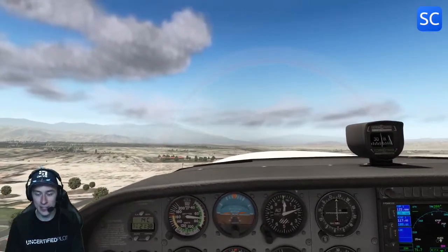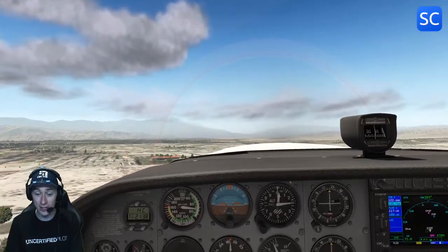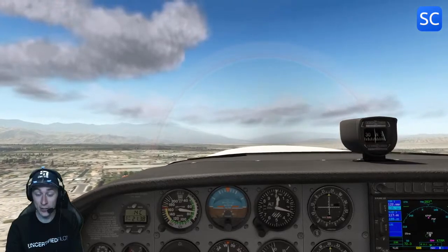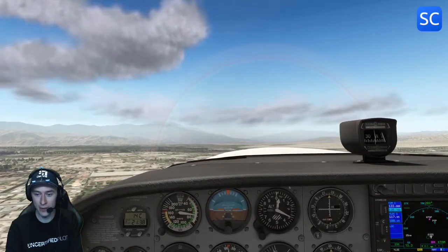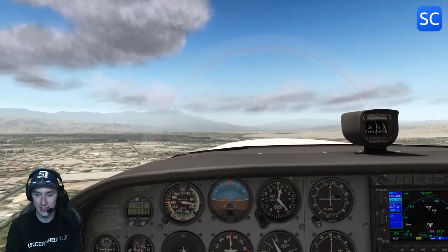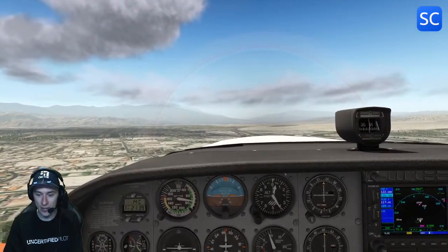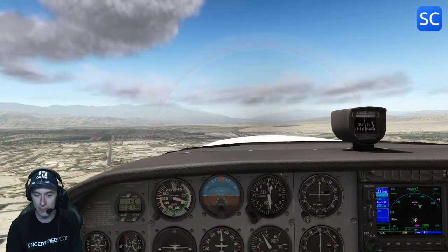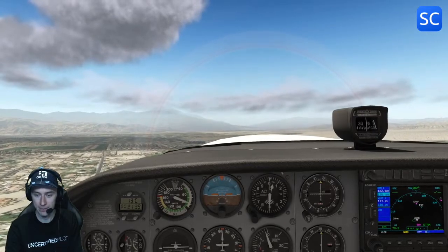It obviously doesn't transmit on the radio, and it just does its own thing. And so as a training environment, I should have noticed that aircraft on final, so I can practice. But clearly I didn't. All right, nose a bit down, Vy, already 300 feet AGL, so flaps up, nose up a bit.